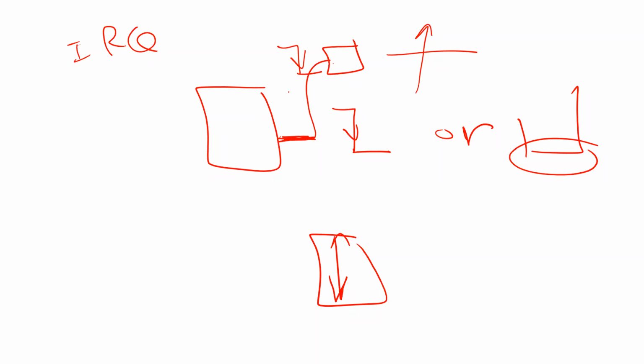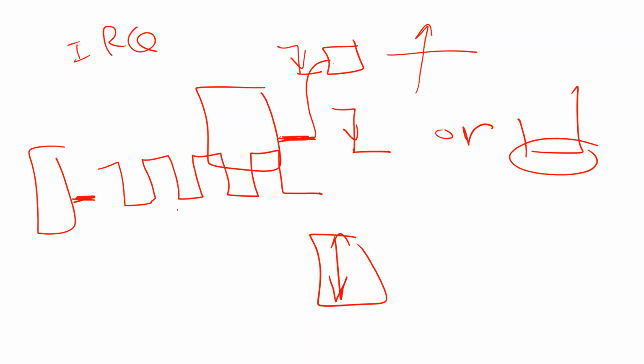Another important thing I told you about, guys, is that I can use IRQ for a frequency meter to measure frequency. How can you do that? Simply, the idea is this is a signal whose frequency I want to measure. Every time there is a falling edge, you are going to trigger an interrupt. This is one interrupt, interrupt here, interrupt here, interrupt here. All I have to do to measure frequency is count how many interrupts happened in 1 second.